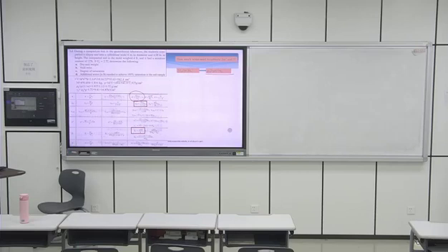So, if volume now is 1, the difference between the saturated density and the moisture density gives you the mass of water you need to add to saturate 1 cubic meter of soil, right? Understand this?